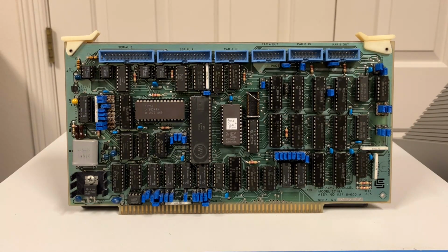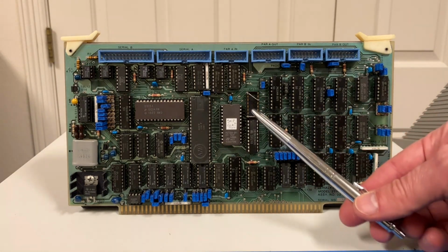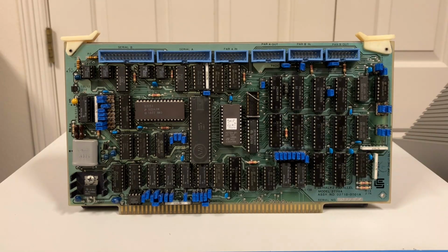Next, we need the status register bits to map to where we need them. We need receive data available, excuse me, on bit 0, the least significant bit, and we need transmit data ready on bit 7, the most significant bit. And like on the IO4 board, we do that with this header right here. This maps bit 0 and this maps bit 7 to receive data available and transmit data ready. Those are now in the right position, and now we need the correct polarity. And we need negative polarity, meaning that it's true when it goes to 0.